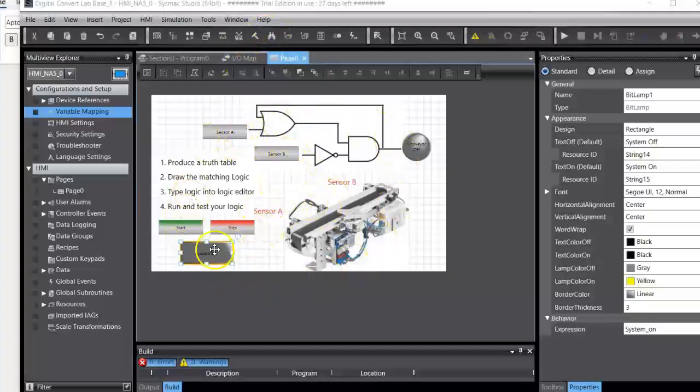Because now it's a fight between, does this one control that variable, or does the real push button control the variable? And usually the push button wins, because every scan, it will detect the push button is released, and the communication with the HMI is not going to be nearly as fast as the communication between the I/O push button on the PLC.